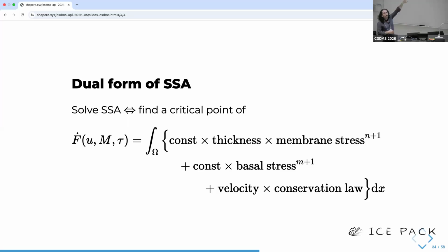So the important part about the dual form of any physics problem is that it inverts all constitutive relations. So in the primal form of elasticity, we express stress in terms of strain. In the dual form, we go the other way. We express strain in terms of stress. Before, I wrote down the strain rate in terms of stress with that nonlinear constitutive law. But when we use the primal form, I have to flip that around to get stress in terms of strain rate. And there I get those powers that are less than 2. When we go to the dual form, we flip the character of all of the nonlinearities. And I think that's what really saves us.